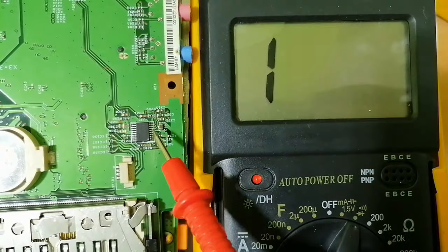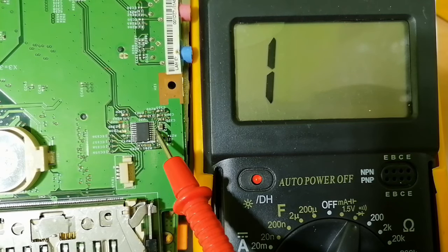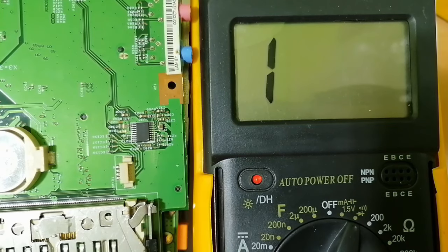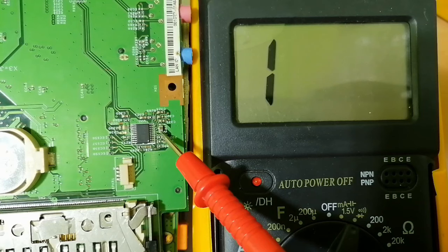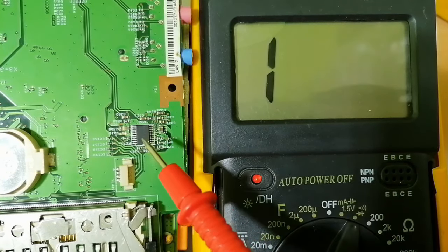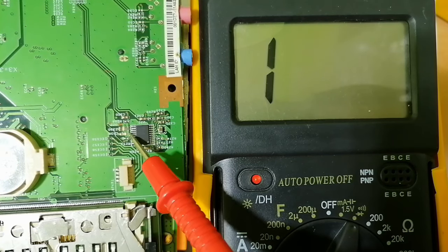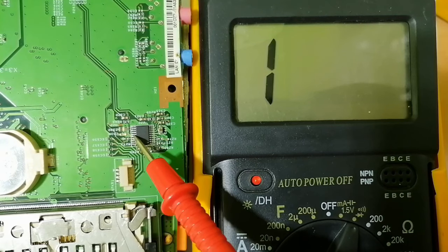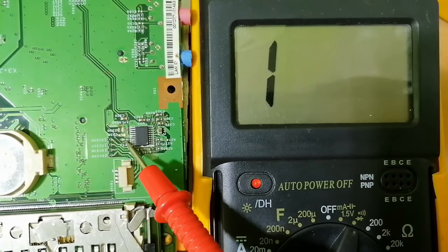Okay, so this information right now we will use to find a short circuit. Because the ceramic capacitors are connected to the IC on one side and to the ground on the other, and of course the IC itself is connected to the ground in one or two of its pins. Do you see here? These two pins basically are connected to the ground. Why?